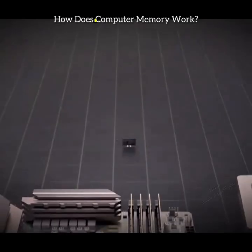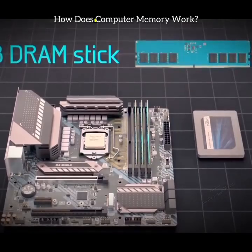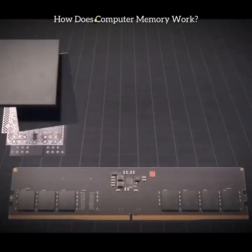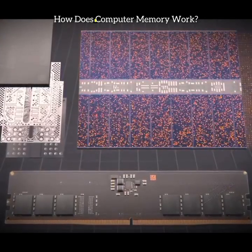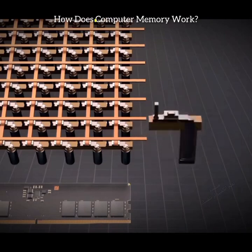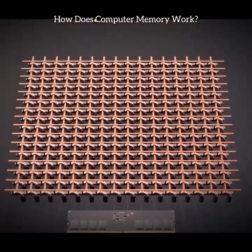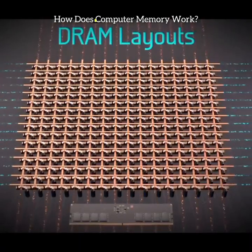We covered solid-state drives in other videos, so in this video we're going to take a deep dive into the 16 gigabyte stick of DRAM. First, we'll see exactly how the CPU communicates and moves data from an SSD to DRAM. Then we'll open up a DRAM microchip and see how billions of memory cells are organized into banks, and how data is written to and read from groups of memory cells. In the process, we'll dive into the nanoscopic structures inside individual memory cells and see how each capacitor physically stores 1 bit of data. Finally, we'll explore some breakthroughs and optimizations, such as the burst buffer and folded DRAM layouts that enable DRAM to move data around at incredible speeds.